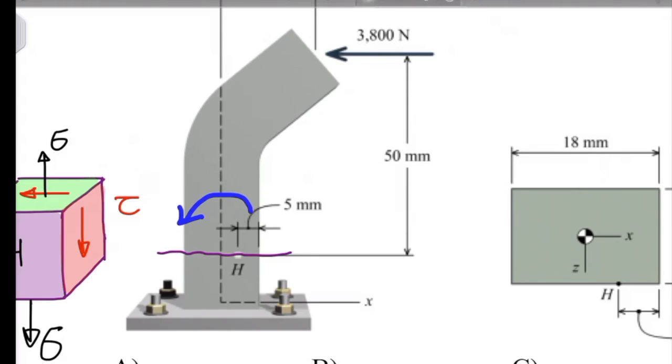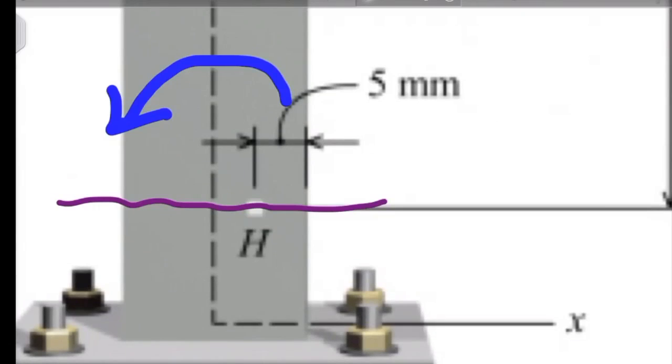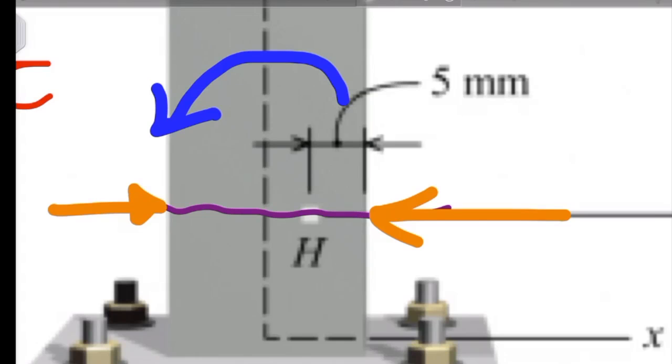The case where we might see normal stress in that red surface is where we have a force acting on this side and another force acting on this side. In that case, we see compressive stress in that surface. Other than that, there is not any normal stress at that point. If there is just one side, there is no normal stress on that side, because that is actually moved downward by shear mechanisms, not by the normal stress.